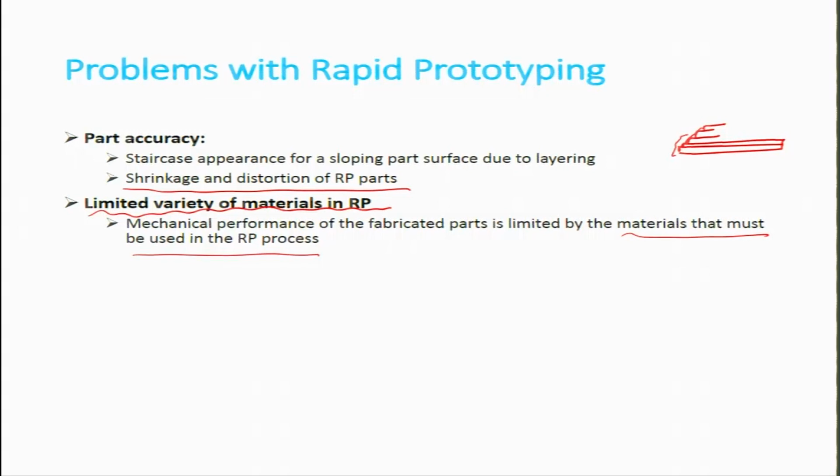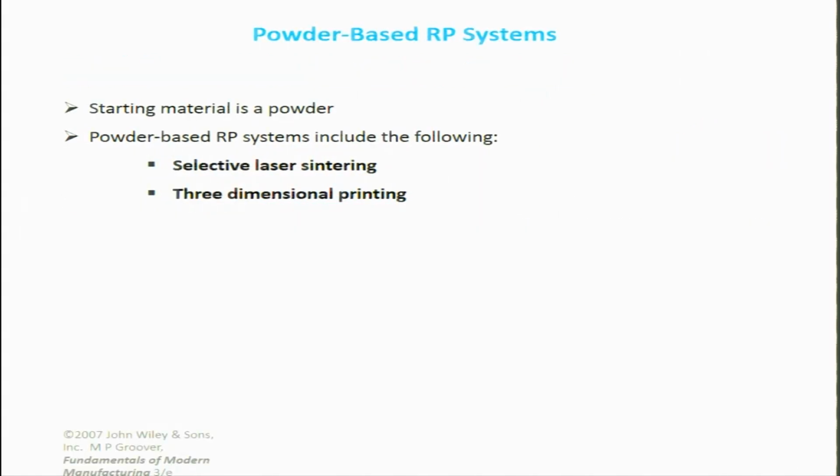And in engineering parts where we need more mechanical endurance, sometimes rapid prototyping or FDM processes particularly may not be a very good option. So, load bearing parts are typically, it is preferred that you make it out of metal and not polymer in most of these systems.